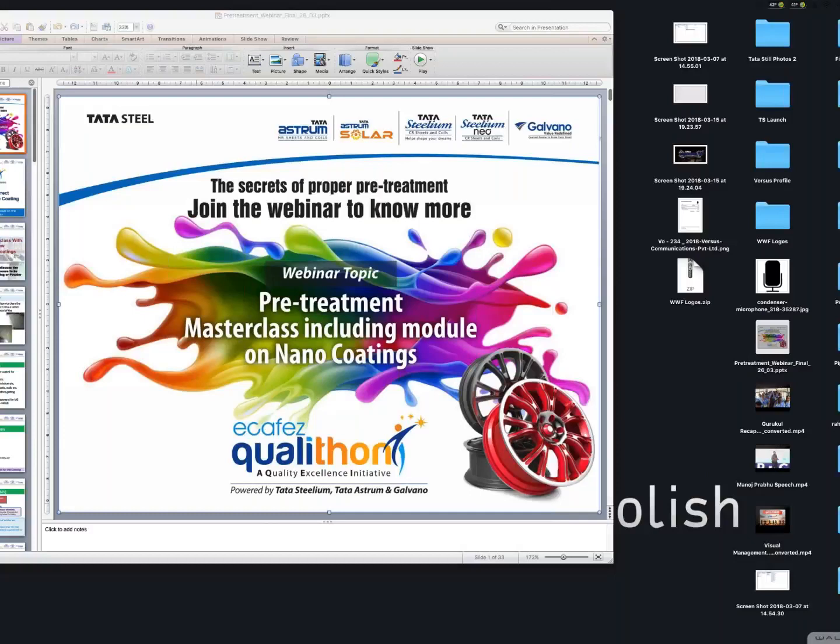Then Mr. Shaktivelan is asking, if chloride of 0.22 to 2.6% was present in RP oil, will it get removed? I think it should get removed because this chloride is not water-based chloride. These are oil dissolving chlorides basically, so it should not be a problem.